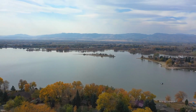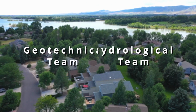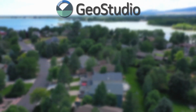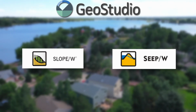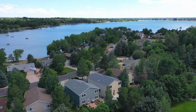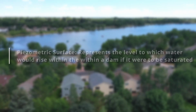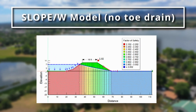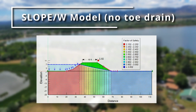Once all relevant characteristics of the dam were collected, we split into 2 separate teams to engage in the 2 modeling endeavors. The geotechnical team used the modeling software SlopeW and SeepW to model the homogeneous earthen dam, and to determine if a toe drain would need to be installed to lower the piezometric surface. It became apparent from the modeling that a toe drain would be necessary to meet regulations, so the process to design an appropriate drain was initiated.